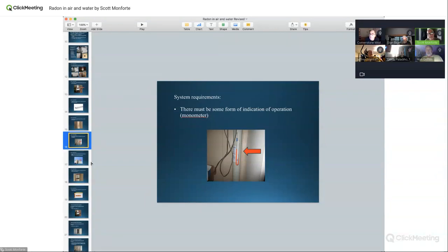A lot of times that little plastic tube on the U-tube is pulled out. I get agents calling me all the time, saying it's not working. I say, take a picture, and the tube is just hanging there. It's not in the pipe. I say, put the tube in the pipe. They're like, oh, you're a miracle worker. We fixed it.